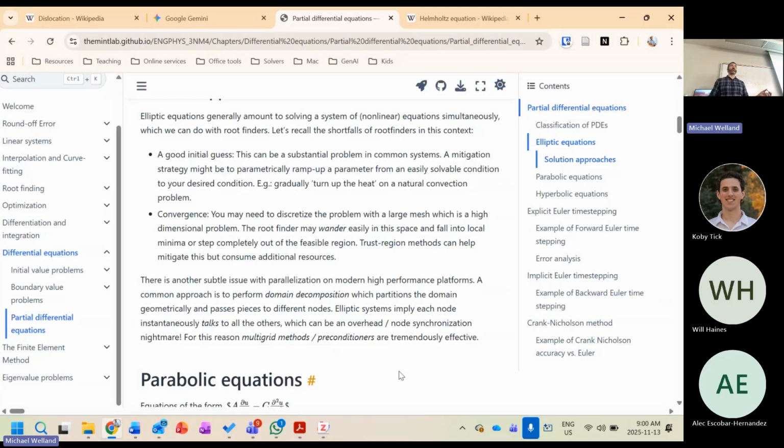In my experience, to be honest, just take a smaller step size. If you have the previous solution, and almost always you will, with the one caveat being the initial value, because maybe your initial value you don't actually know very well. Maybe your initial value doesn't actually solve physics consistently, which is also unfortunately a problem, and COMSOL has a setting for that.